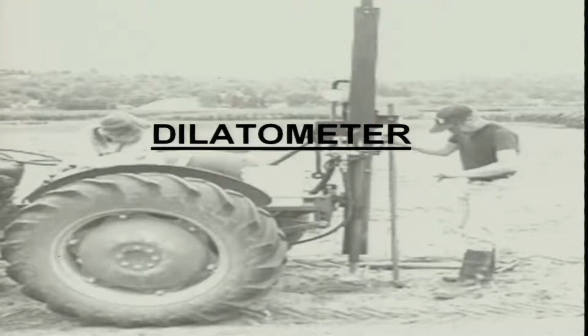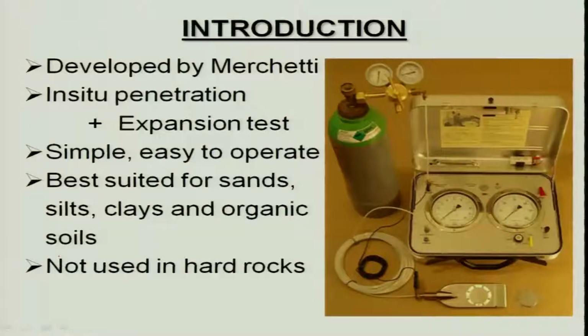Then the next test is your dilatometer or pressuremeter test. I will have to go slightly faster from now onwards because there is a lot of course content and syllabus. The main focus is your foundation design, so these are all basic site investigations. The dilatometer was developed by Marchetti. It is an in situ penetration plus expansion test, simple, easy to operate, best suited for sand, silt, clay and organic soils, not used in hard rock.